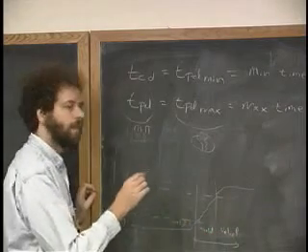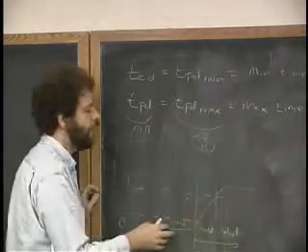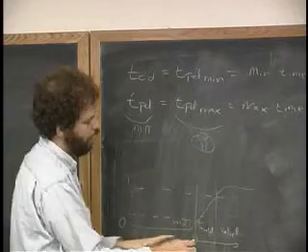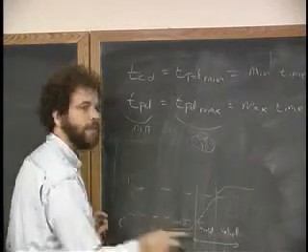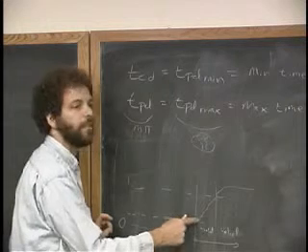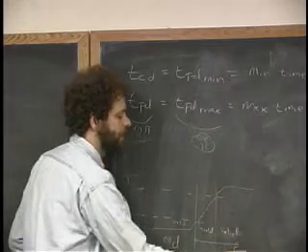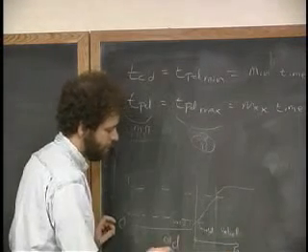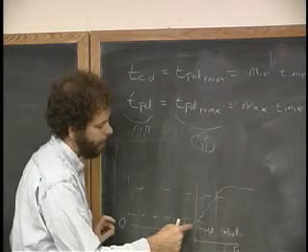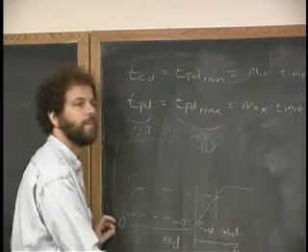Any signal is going to go through these three phases as it switches from a 0 to a 1. From valid to invalid, back to valid once more. And so the question is, if I have a circuit and I feed a signal like this to it, how long does it take between when I no longer am sending it a 0? This is the old value, and here's the new value. And the circuit, given the old value, is producing an old result. How long after I no longer feed it the old input does it still produce the old result?